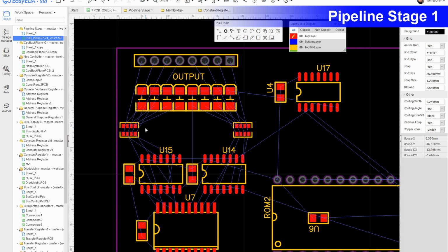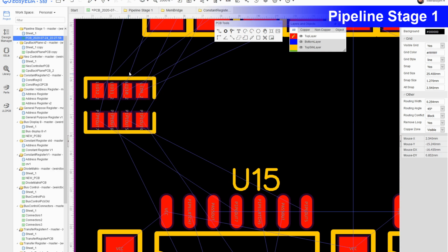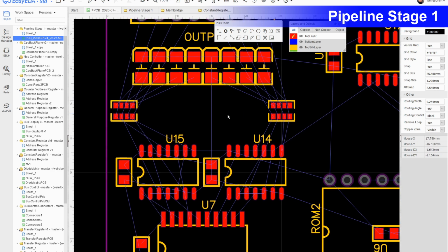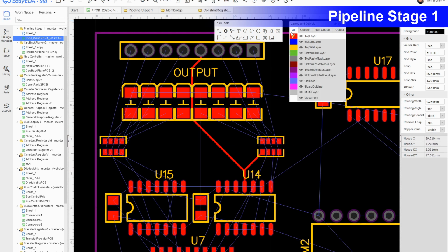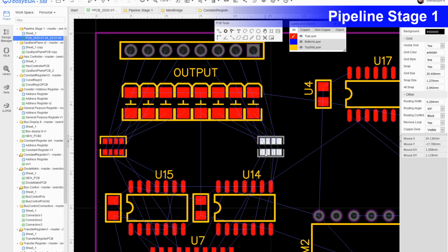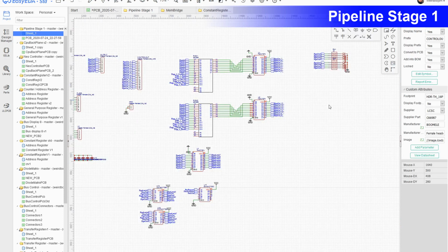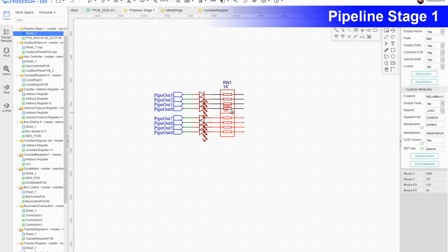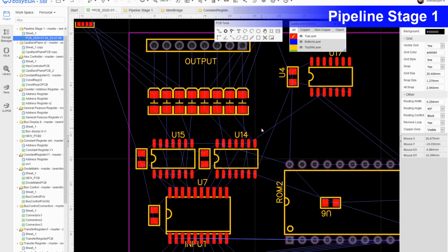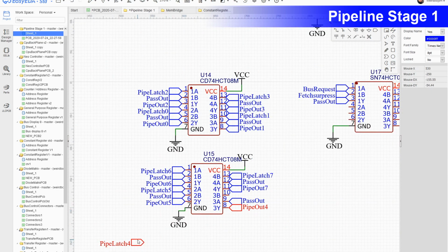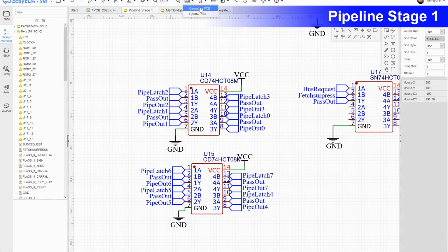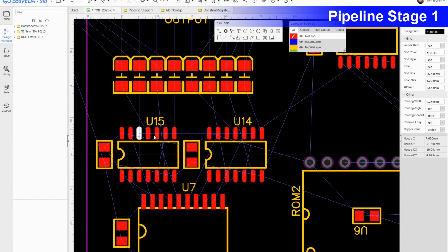This would potentially be easier to route without the resistor arrays. I haven't got space to put traces in between the pads on these things. I think it will be better to have the resistors on the other side. So I want to swap these two over. And I need to swap the other pair as well.